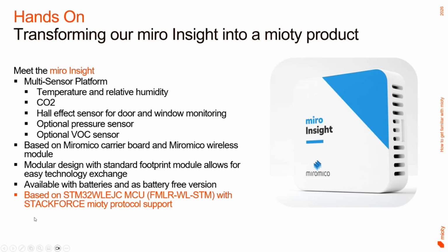So now to take you on the journey, the first mioty product that we launched and that we ported from LoRaWAN to mioty was the Miro Insight. This is a multi-sensor platform with a couple of different sensors: temperature, CO2, humidity. It's also a door sensor, pressure, and VOC. This one is based on a Miromico custom carrier board and our own wireless module.